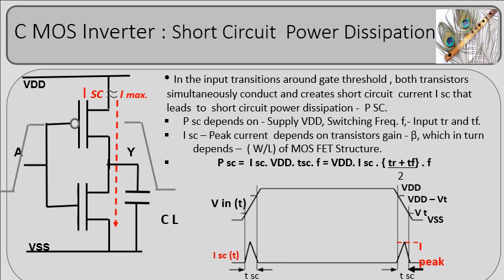Short-circuit current of a CMOS inverter occurs during the switching transition, when both N and PMOS transistors, for a very short period, are in the on state and conduct current across the supply. During the inverter transition period, due to poor mobility of holes, the PMOS switches off slowly. That is, even after switch off, for a short period it continues to be partially in the on state.